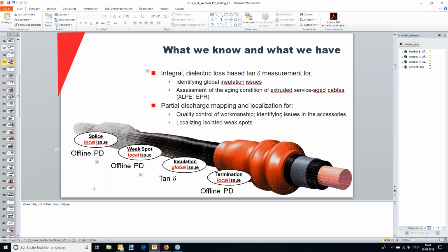I mean, every method has its limits, but that kind of localization based on TDR and traveling wave and this reflection analysis is already better than anything else, in terms of doing a real measurement. You can see really far into the cable, and depending on the cable, rule of thumb, on average, 2, 3, sometimes 5 kilometers. Sometimes 10, depends.